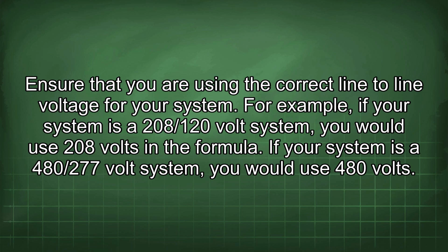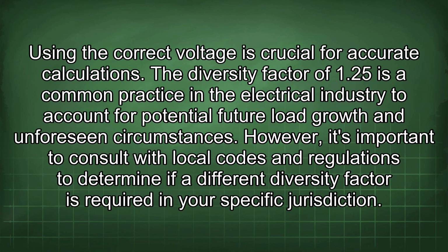For example, if your system is a 208/120 volt system, you would use 208 volts in the formula. If your system is a 480/277 volt system, you would use 480 volts. Using the correct voltage is crucial for accurate calculations.